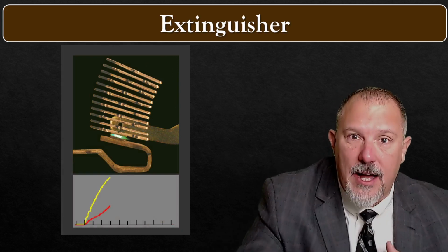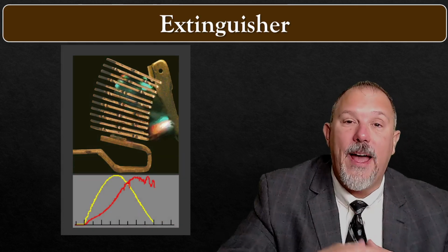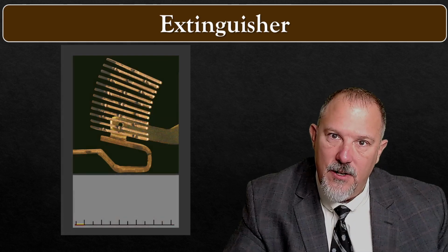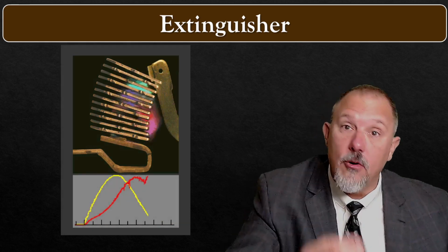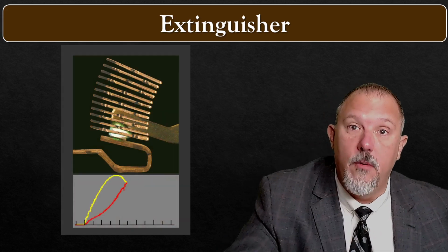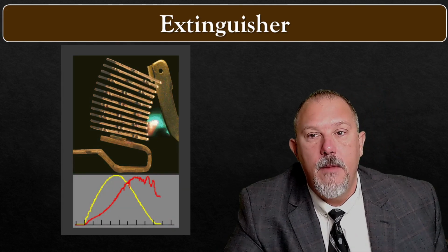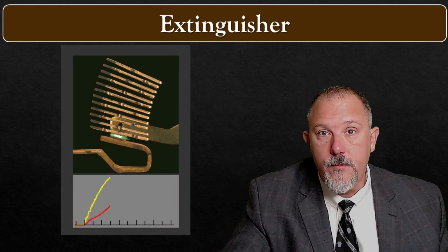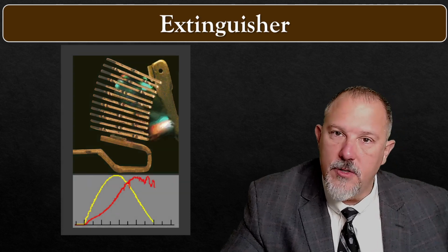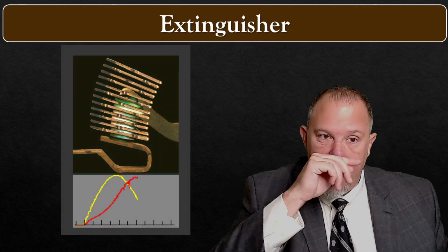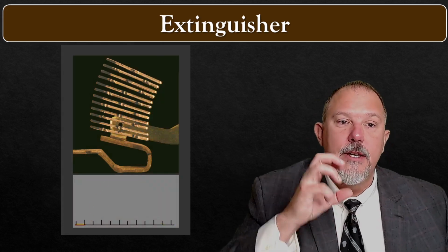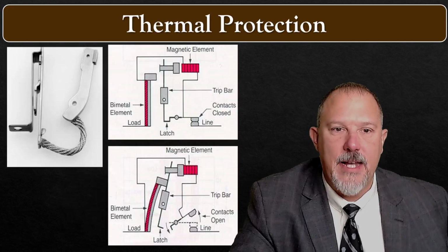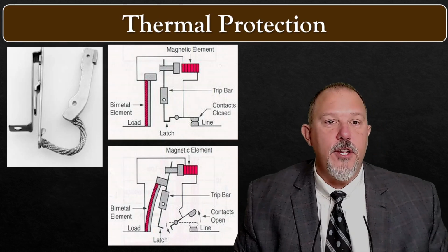And then on the other side of the arc extinguisher, you have arc chutes, which help vent the gases that are expelled due to the interruption, the stopping of the flow of current in that device. Every circuit breaker is going to have an arc chute that expels those gases. And then the arc extinguisher helps extinguish and cool that arc and stop the flow of current. It's magnificent.